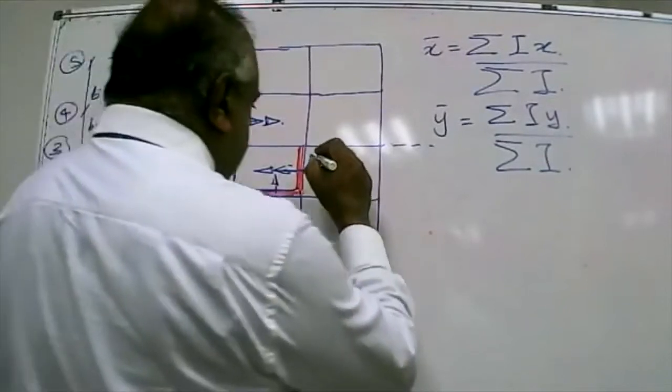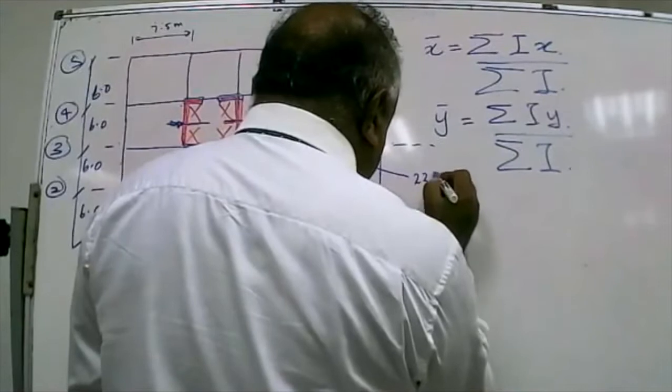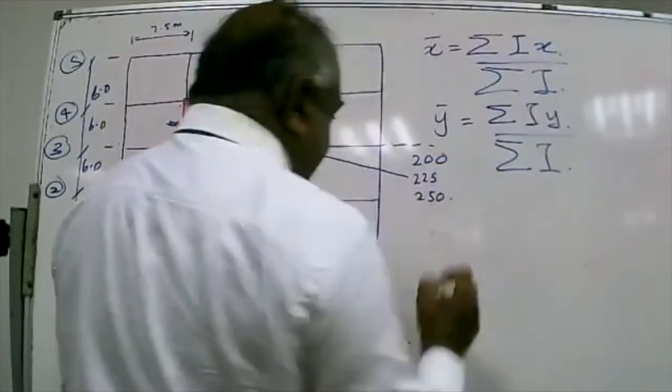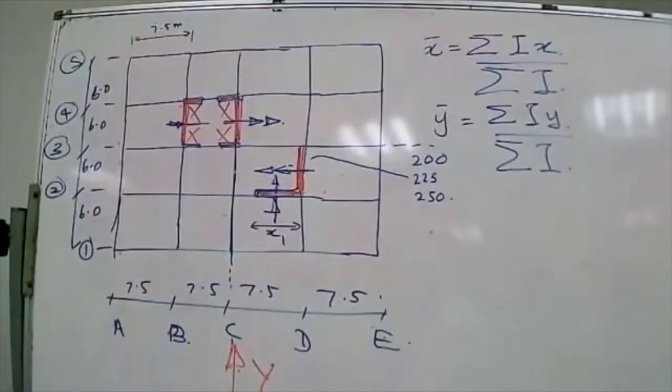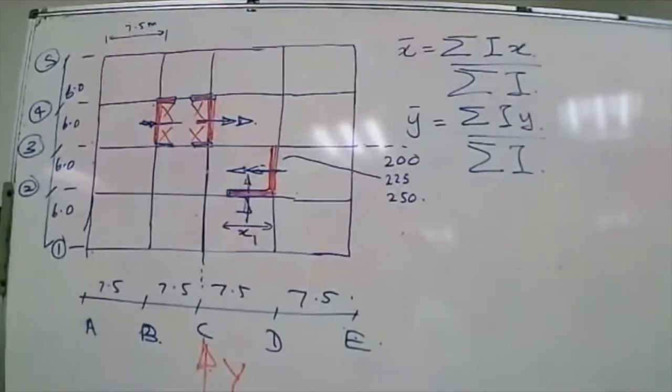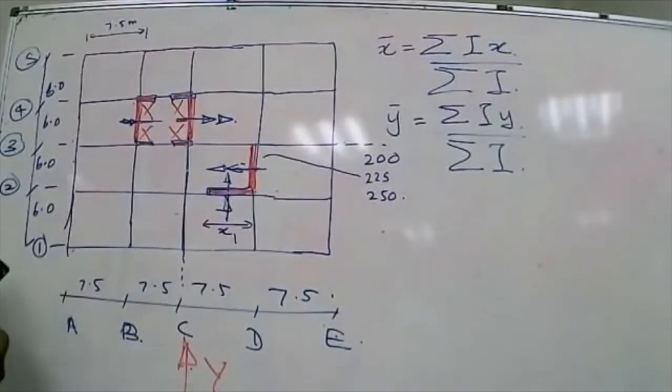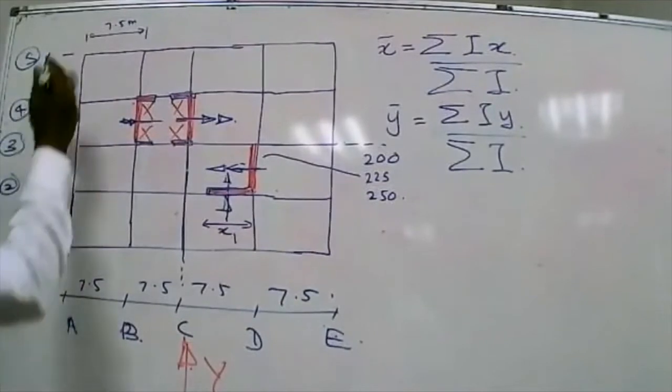And because it's a 10-story building, we can go for 225 or 200 also possible. It's a little difficult to concrete. So if you go for 225 or 250 walls, then it's much easier to concrete. You lose only 50 millimeters or 25 millimeters, but still you'll find that the concreting operation is very easy. So if you take this structure, we'll have walls and columns.